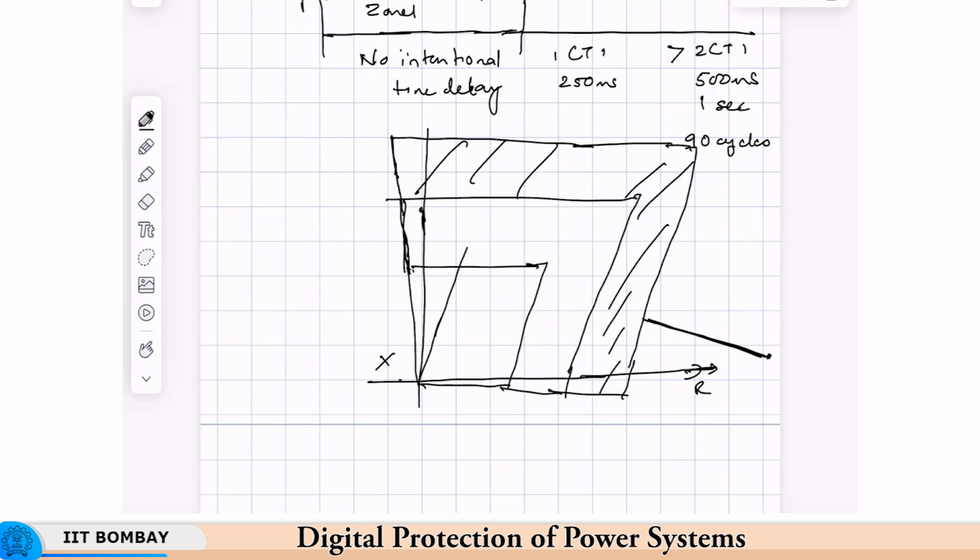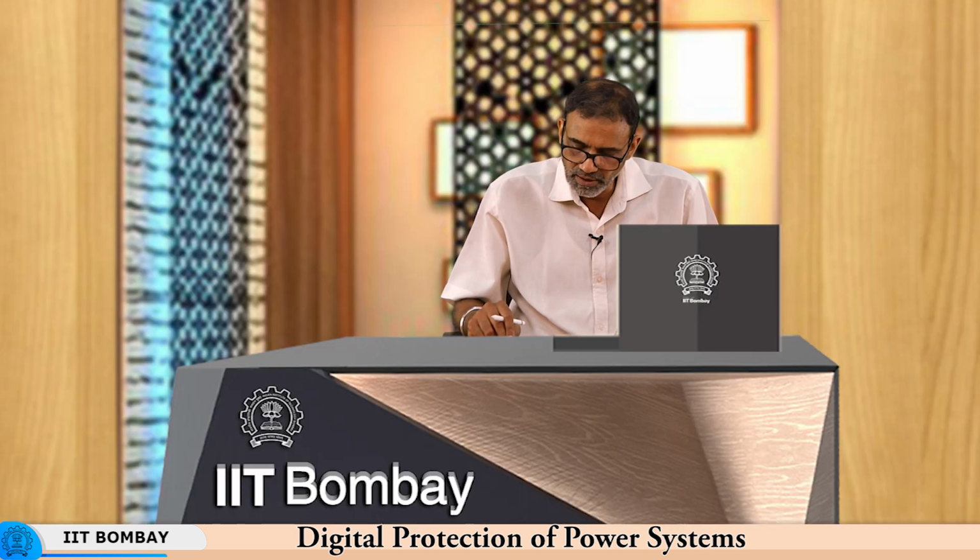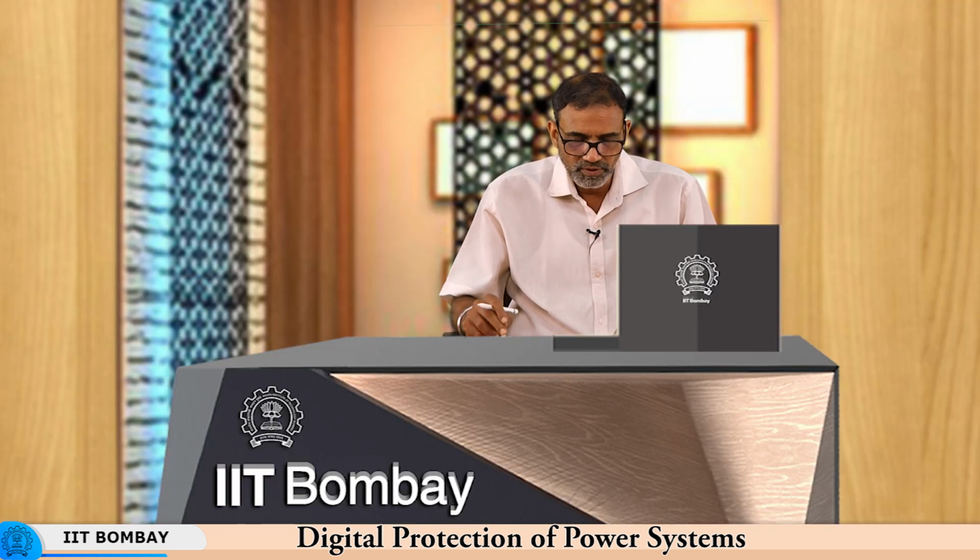Those power oscillations appear as oscillations here on the RX plane, and then if they encroach this characteristic for a long enough time, meaning if they stay within that characteristic for a time greater than this time, that is 500 milliseconds or 1 second, whatever the relay setting is, then the relay will issue a trip command, because it has no way of knowing whether that event is a fault or a power swing.